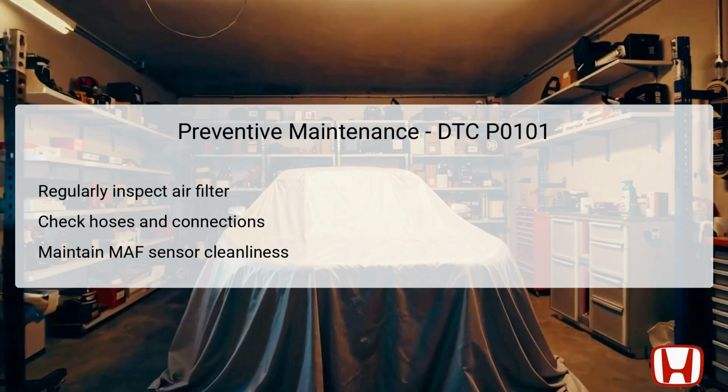Additionally, routinely check hoses and connections for wear or damage, since proper airflow and pressure are critical for the MAF sensor's accuracy. Any issues in this area can lead to problems. Furthermore, consider periodic cleaning of the MAF sensor itself with special cleaning products specifically designed for that purpose to ensure it operates within the expected range.